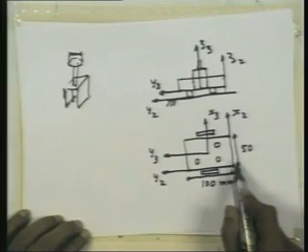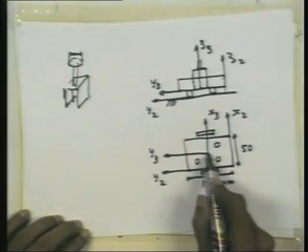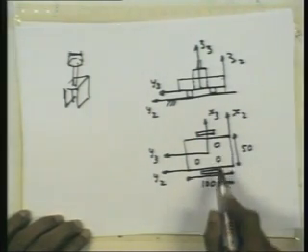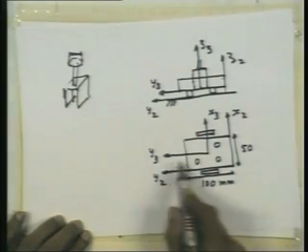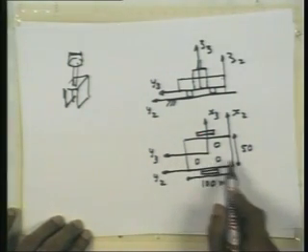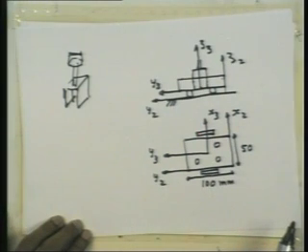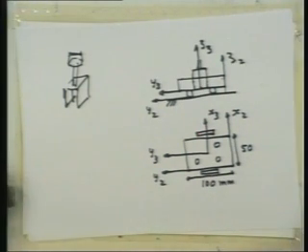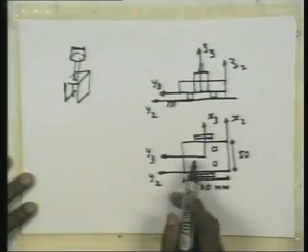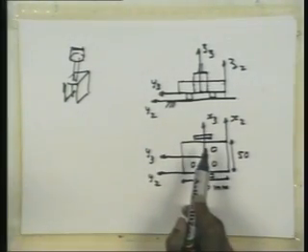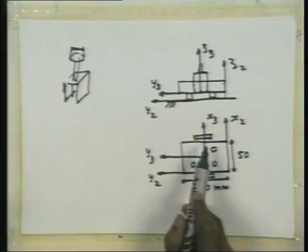Since this is 50 millimeters from this edge, this particular point will be 25 millimeters from this edge. Now if I center it in this direction also, this will be 50 millimeters from this edge, right? So now I can specify the position and orientation of the gripper reference frame, that is the end effector reference frame, with respect to the object reference frame as follows.